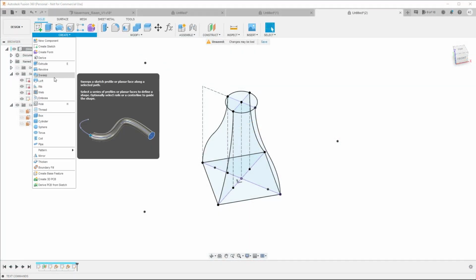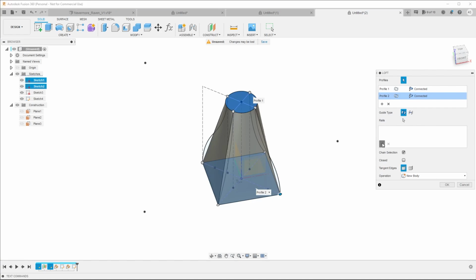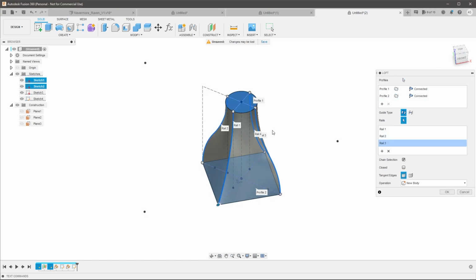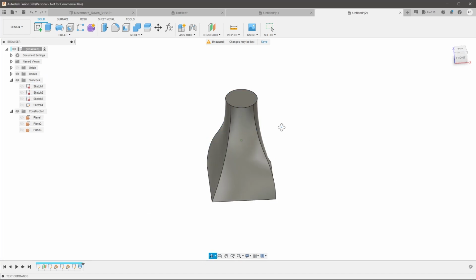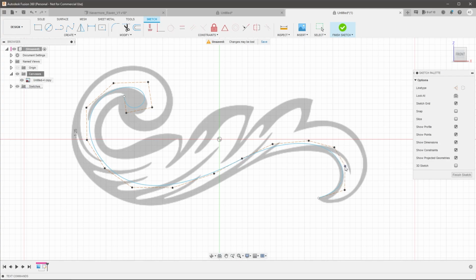Predictability in CAD should not be underestimated, as having fully defined shapes sets the rules for all of our modeling tools. If we have a defined shape, we know what to expect when we loft along that trajectory or make changes to other dimensions in our design. Now, this is not to say that full definition is impossible with splines, or that there is no situation where they are the right tool. But knowing when and when not to use them is the real challenge.